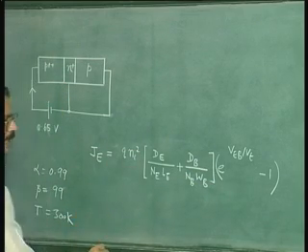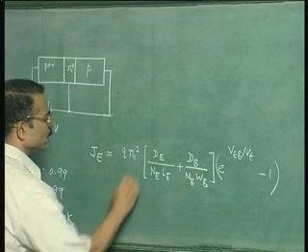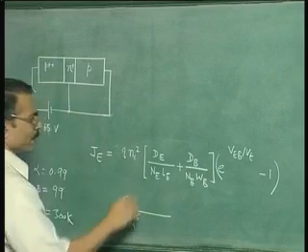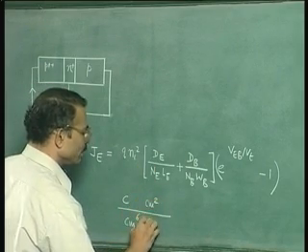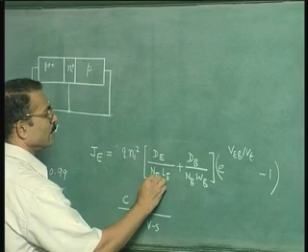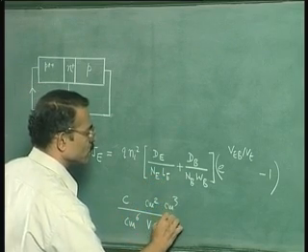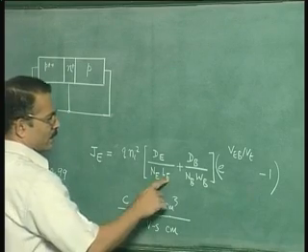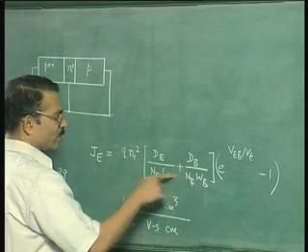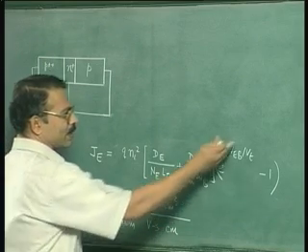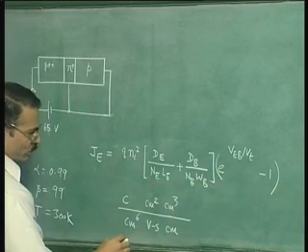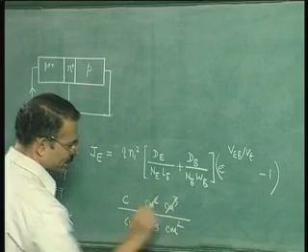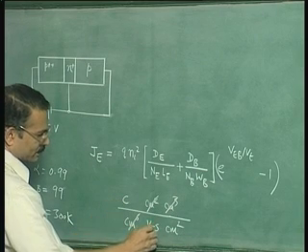Okay, let us do an exercise here. For example, this is Coulomb, Ni square is centimeter power 6 in the denominator, diffusion coefficient is centimeter square per volt second, doping is per centimeter cube, so it goes in the numerator, and this is centimeter in the denominator. This quantity also will have the same dimensions as this quantity, so we need not consider this. Similarly, this is dimensionless. Now here you find this will cancel, and here you will get centimeter square. Coulomb per second